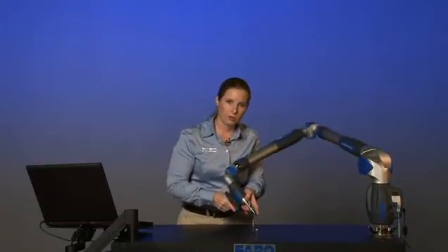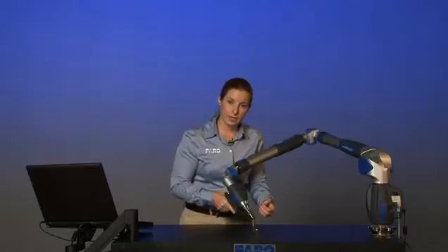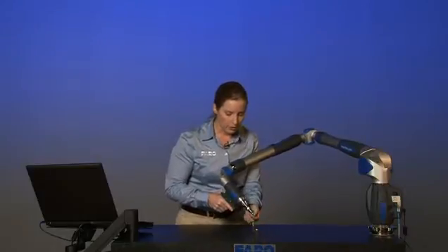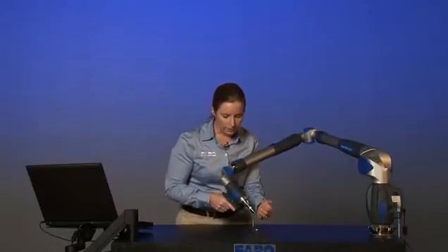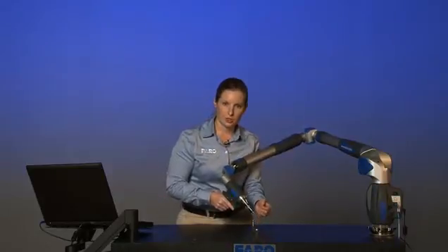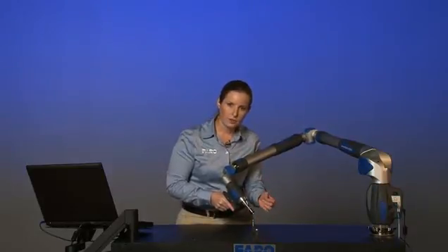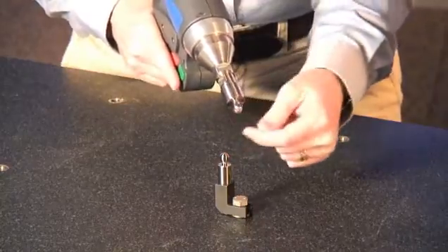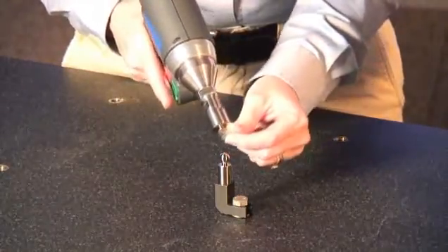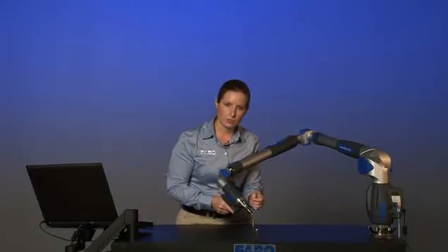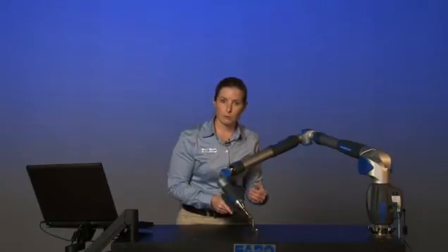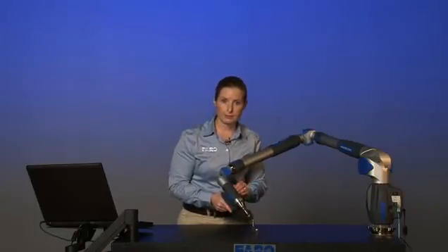For the swivel probe, we're going to do a standard sphere calibration in which we touch the ball of the probe to the ball of the calibration sphere. It's important as you're calibrating to make sure that you're touching the spherical surface and not the cutout surface to the calibration sphere. We're going to take 44 points in 4 sets of 11.